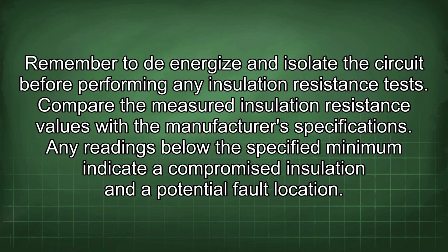Remember to de-energize and isolate the circuit before performing any insulation resistance tests. Compare the measured insulation resistance values with the manufacturer's specifications. Any readings below the specified minimum indicate a compromised insulation and a potential fault location.